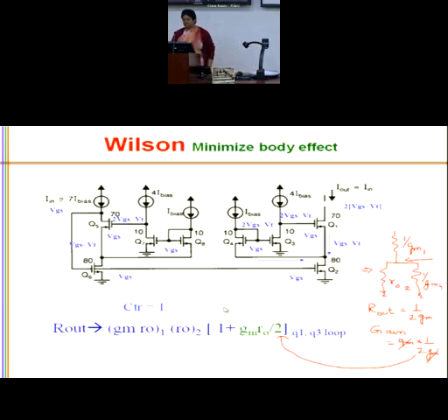So look at the slide. This is the gain boosting that I am doing. It is an amplifier, whereas this is my common source amplifier, and this is just to propagate the perturbation, the node voltage variation, from this node to this node. And once the perturbation reaches here, this common source amplifier produces minus gain times the input. So this gate reduces, so VGS reduces. Any increment here causes a decrement at this node.